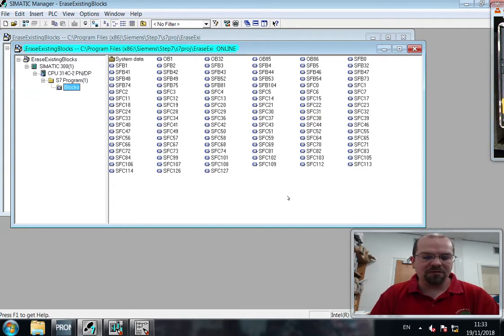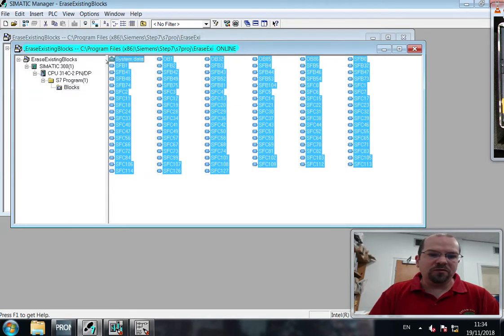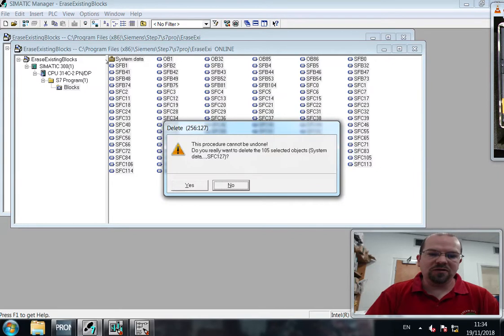But we'll select all of the blocks. Press delete. OK. Press yes. Remember, the system function blocks cannot be deleted online. Yes.